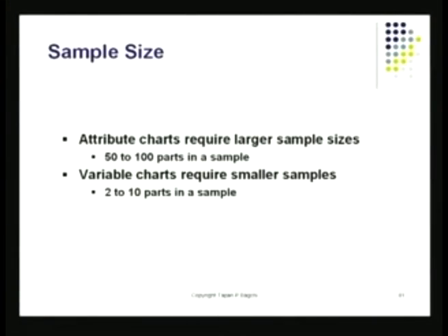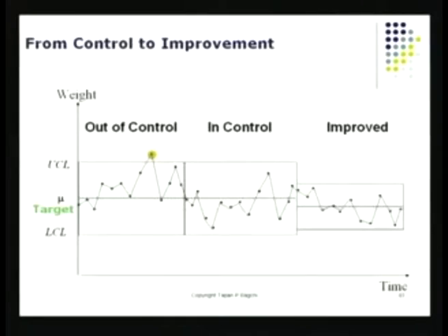If you're looking at the variables chart, what should be the size of your n, which is like the subgroup of items that you decide to pick every time? So I collect so many data points and I average them out. I calculate one value of X bar and one value of R. How many data points do I need? It should be between 2 and 10. If you do that, it will be very easy to go to the table there and find your quantities.